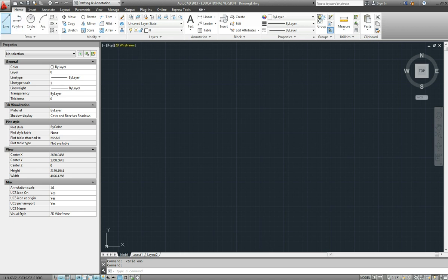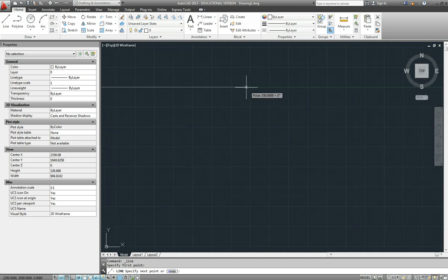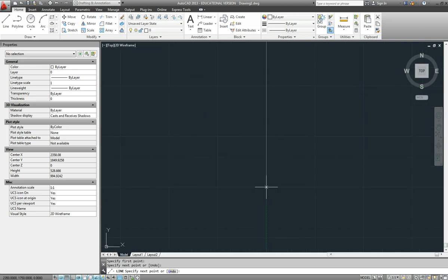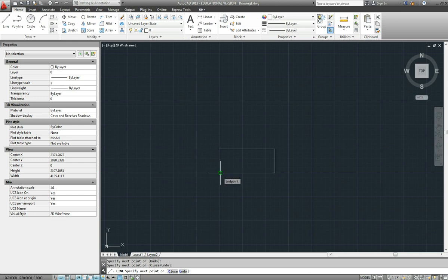Now when we go into line drawing with the snap on, we start drawing, you'll notice that the mouse is actually snapping to those points. It's very difficult to actually draw in between those grid points. It just jumps from one to the other. So if you're drawing something that is in 5mm increments or 10mm increments, then that's quite a handy way to draw without doing any measurements. You can just sort of count across and draw it that way.